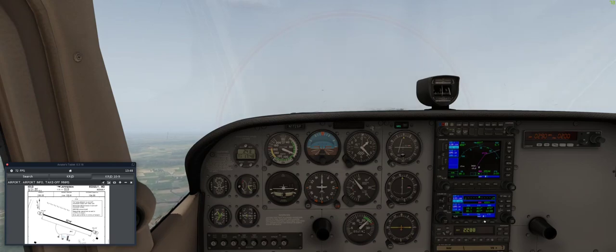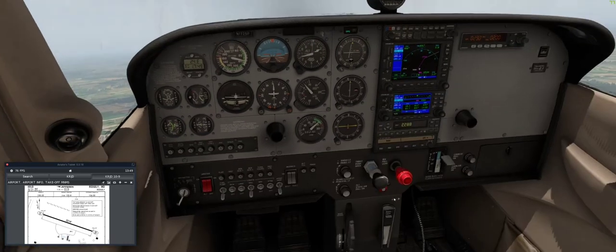We see airspeed is dropping. The autopilot in this aircraft does not control your throttle. You do. So I'm giving it a little bit more power. We want to keep it at about, I think 74 is the ideal climb for this aircraft. If it continued to go down and I didn't have any more power to give, then I'd have to choose